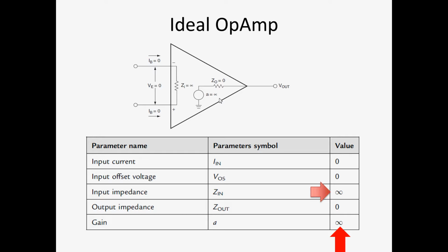It means that if you have 1 volt at the input, you reach your maximum output. If you put 2 volt at the input, the amplifier is still going to try to gain 10, but 2 times 10 is 20, which exceeds the 10 volt. What is going to be the response of your amplifier? A flat line at 10 volt.